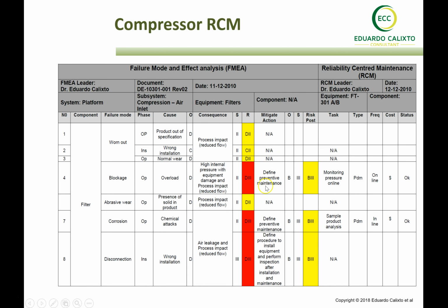We need to define preventive maintenance for that, and so we have online pressure monitoring for the filter. The other critical issue is corrosion from chemical attack, so we need to take some product samples. That was the action defined during the RCM here. That will be online.